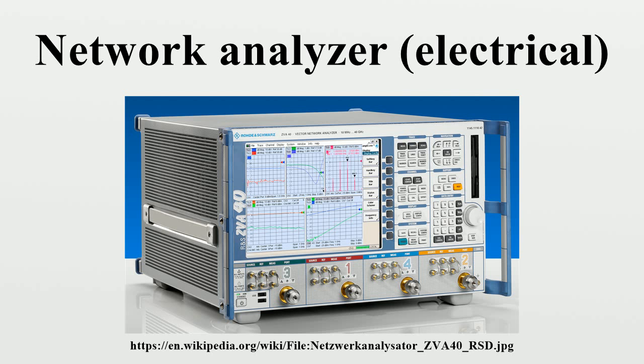In a VNA, the reference channel goes to the receivers. It is needed to serve as a phase reference. Directional couplers or 2 resistor power dividers are used for signal separation. Some microwave test sets include the front-end mixers for the receivers. The receivers make the measurements. A network analyzer will have 1 or more receivers connected to its test ports. The reference test port is usually labeled R, and the primary test ports are A, B, C.